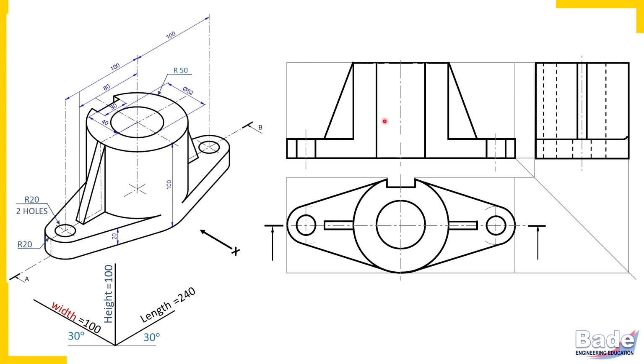No hatching lines here. This rectangle here at the center, that is inner surface of the hole. It is original surface which is getting exposed after cutting. It is not newly generated surface because of cutting of solid portion of the object. Here solid portion of the cylinder and the solid portion of plate gets cut. That is why this is a newly generated surface.